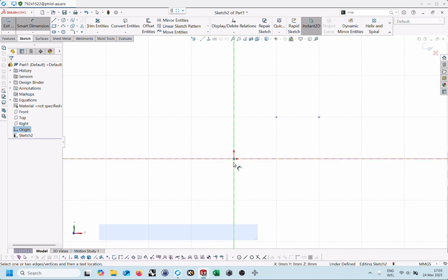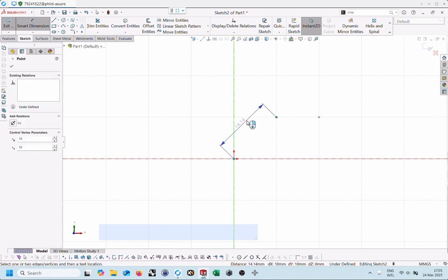From the moment you click on the origin, SolidWorks doesn't know whether you want to reference the x-axis or the y-axis or something else. It doesn't really care, because the moment you select this next point, you'll get this third dimension, this one you can pull out to the left, upwards or down, and the moment you pull your mouse either to the left or to the right, top or bottom, the dimension changes to being parallel to, in this case, the y-axis, or parallel to the x-axis. That's what position dimension means, parallel to one of the axes.